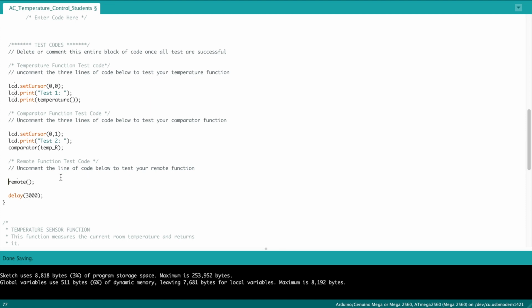Again, remember, you need to remove the LED plus, that is the backlight LED. You need to connect that pin to pin 9 instead of VCC on your breadboard, and that is how you will know whether or not your remote code is working. Once you turn it on, your system should come on, which means the backlight should turn on, and then the backlight should turn off once you turn that off.